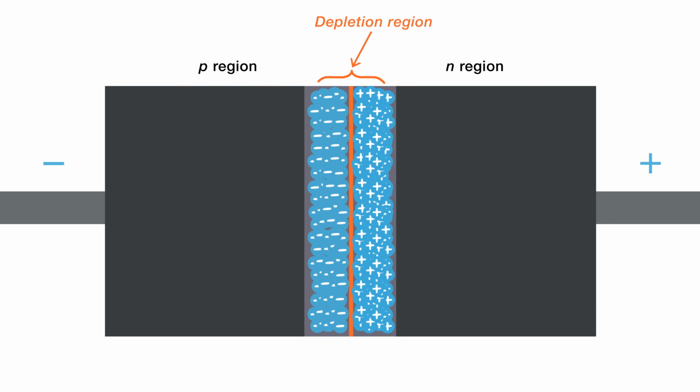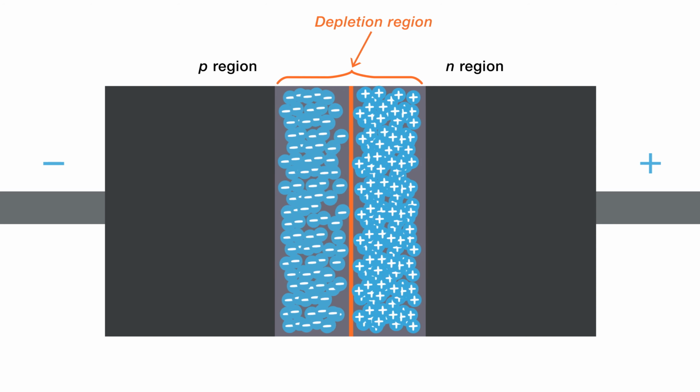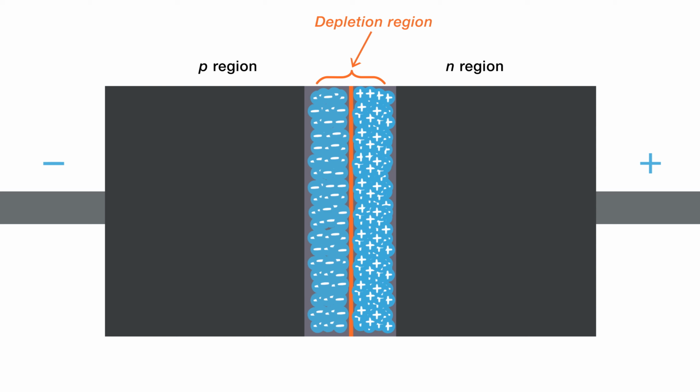As stated earlier, one characteristic of a diode when reverse biased is that the depletion region varies. When the reverse bias on a VariCap diode is increased, the depletion region widens, increasing the separation between the p-type and n-type regions, thus decreasing its capacitance. When the reverse bias is decreased, the depletion region narrows, decreasing the separation between the p-type and n-type regions, thus increasing its capacitance. Therefore, varying the amount of the applied reverse bias on the VariCap diode varies its capacitance.